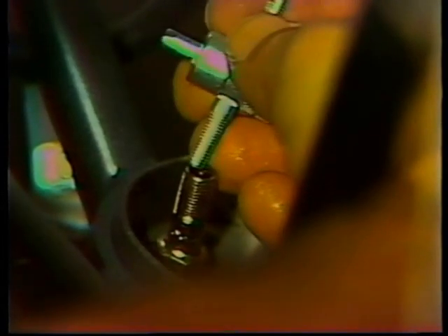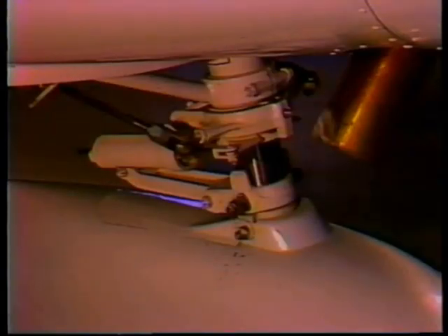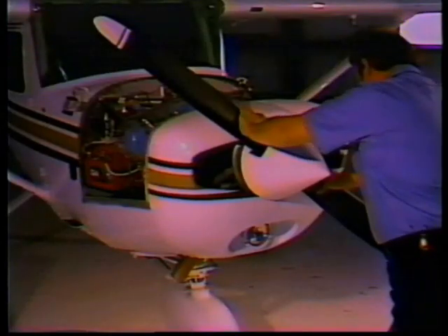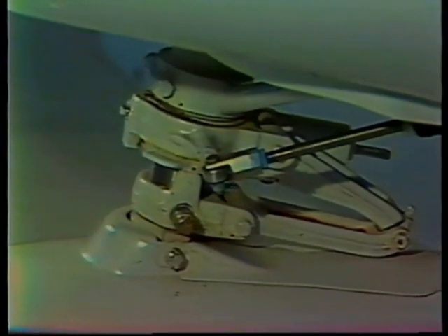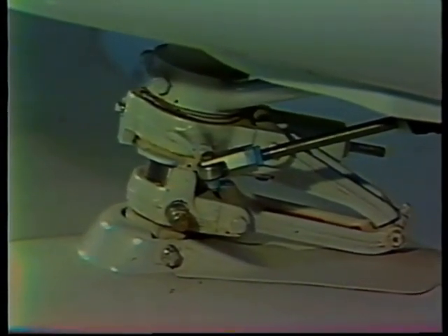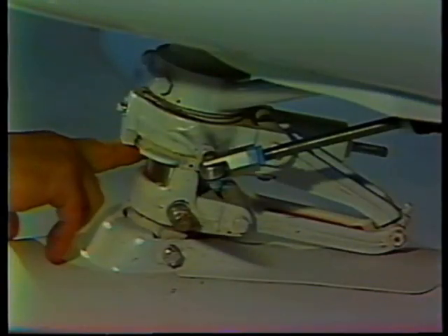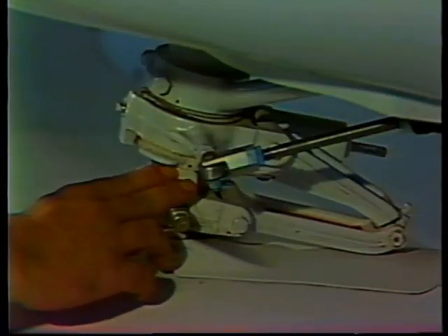Wait until the fizzing of the air and fluid stops and the strut is completely collapsed. In addition, anticipate the rapid dropping of the aircraft when the air is released. Remove the valve core. In some cases, it may be necessary to rock the aircraft after the valve core is removed to be certain that the strut is completely compressed. Visually check the strut to make certain that it's fully collapsed.